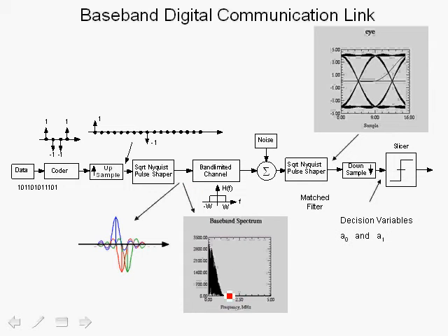We're actually showing the results of a simulation here, and we see the characteristics of a raised cosine filter, and it is band limited to 1.25 megahertz. The bit rate is 1.25 megabits per second, and since we're using 100% excess bandwidth or a roll-off factor equal to 1, the bandwidth is also 1.25 megahertz. The bandwidth of the channel W is also equal to 1.25 megahertz.